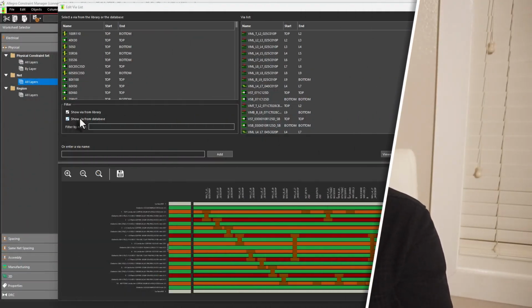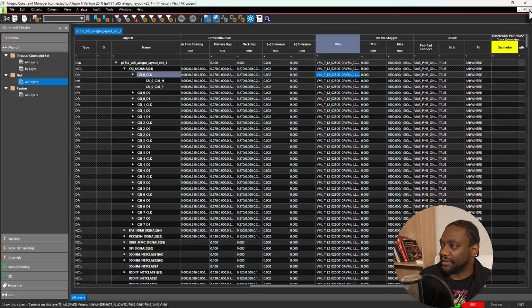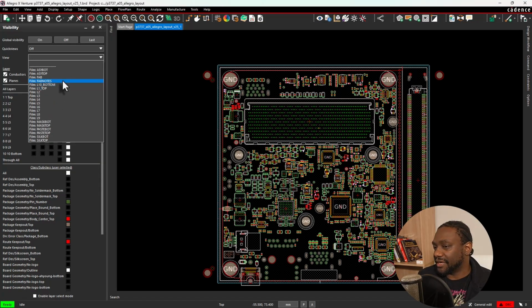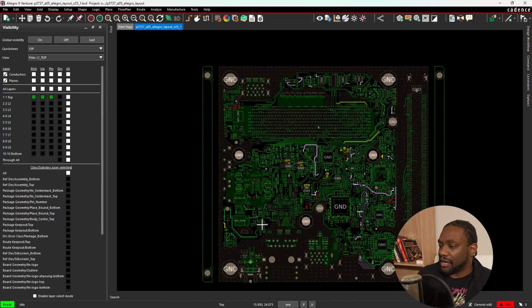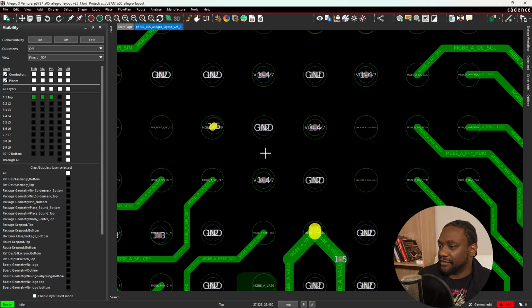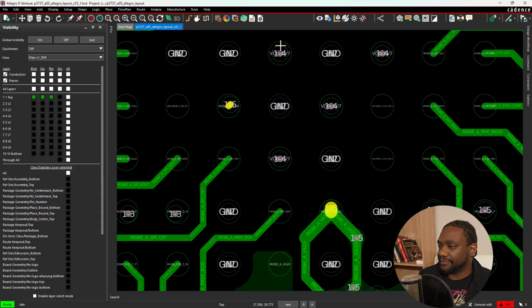Now that we understand the different via types, I'm going to show you how you can make them. So check this out. How do you even make the vias that go in this via list? I'll show you. We go into our design, hit cancel, and X out of here. Then I'll go to my top copper layer underneath this BGA device. The vias show up here. They're like these little circles inside the pads of these ground pins.